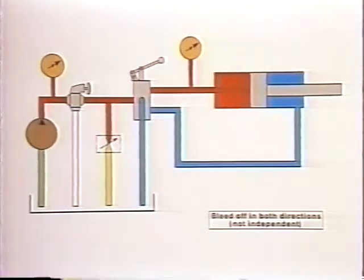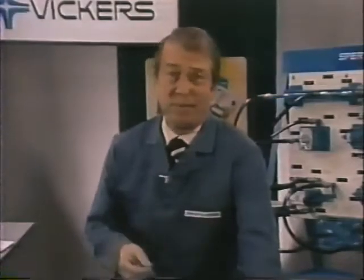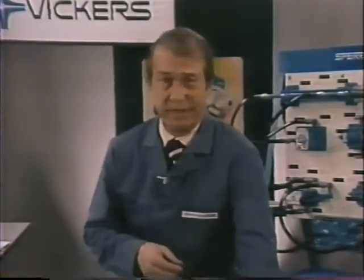This is known as a bleed-off circuit. In this case, unlike the meter-in or meter-out, there is no excess flow going over the relief valve, and our pump operates at only the pressure that's needed to move the workload on the cylinder, and this saves energy. The bleed-off circuit will not prevent it from running away. As with a meter-in circuit, we'll have to use it with opposing loads only.